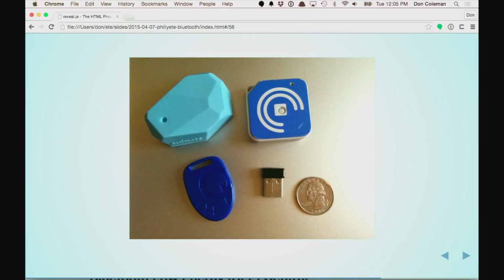If we go back to GAP, when we're talking about Bluetooth and finding and connecting devices, the way beacons work is they're a connectionless protocol. These devices sit there and advertise as a broadcaster, and in this case the phone would be the observer. It's basically just scanning, asking what's out there, reading that advertising data, parsing some of the manufacturer data, and it can actually get information from a beacon without any connection. The important thing to remember is that this flow of information is one way. It goes from the beacon to the device. So it's kind of like the guy standing out in front of the mattress store with the big stupid sign saying, hey, something's here.